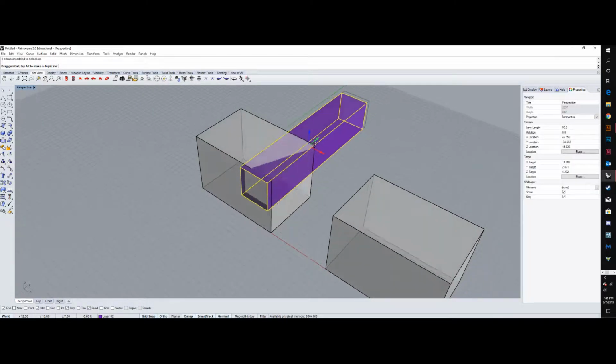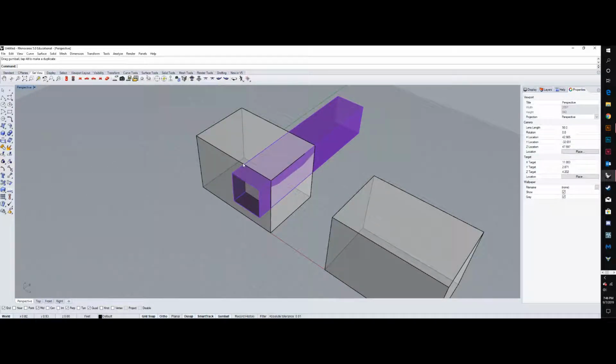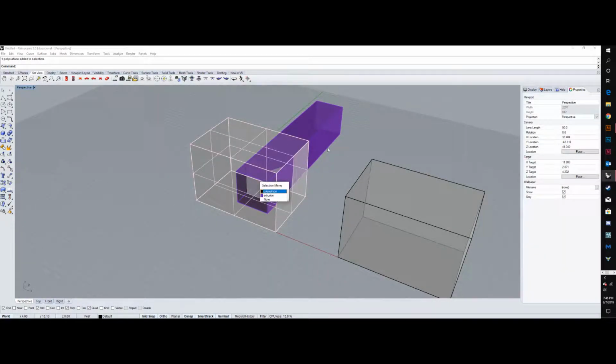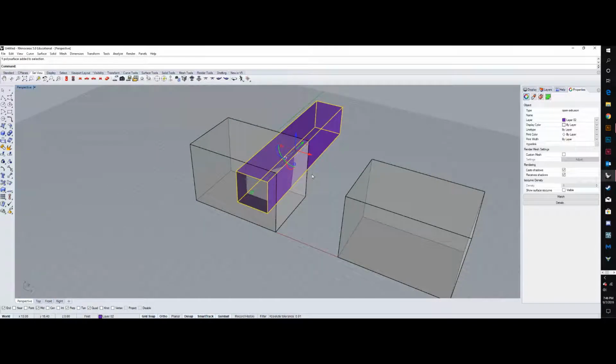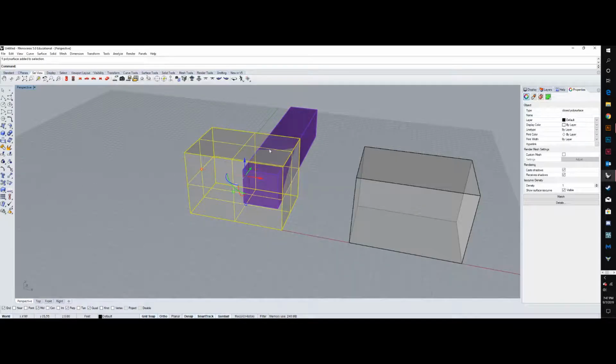I'm going to move it over also, just so that whenever I remove this, I know that I'm not going to have a little bit hanging off. I know that I'm going to have all of this removed. Notice this, before I start removing from this object, I need to go ahead and cap this extrusion. Okay, now that I've capped that, and these are two complete 3D objects, I can remove from this one by using this object with a command called BooleanDifference,